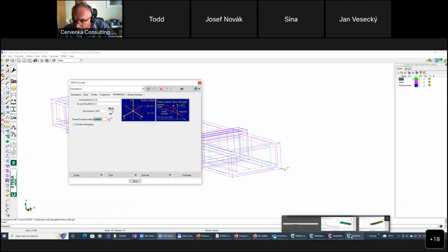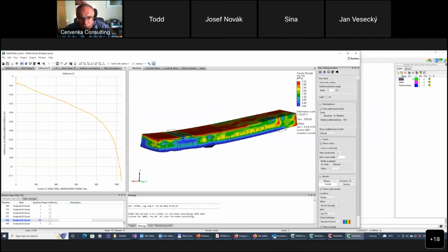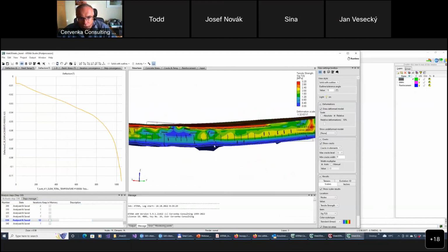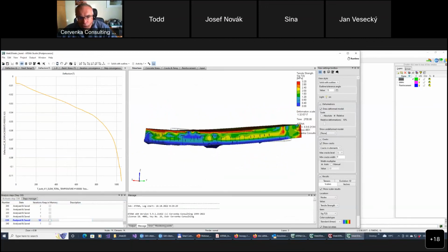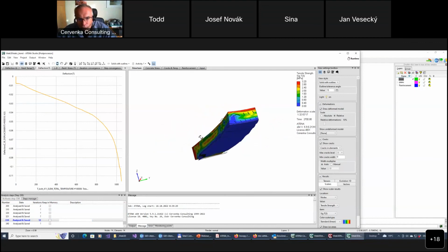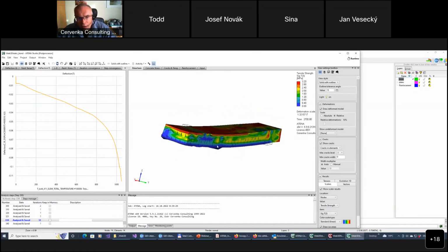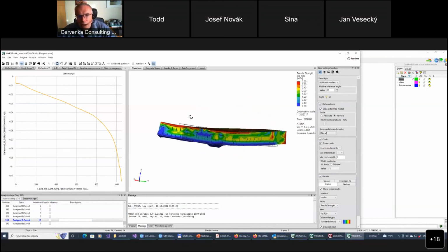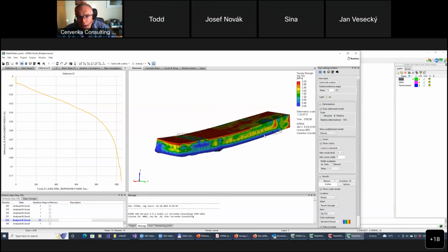And actually, if you look at the results that I showed you, you see that even our model without this water pressure is exhibiting this spalling. You see how this first layer of concrete is being cracked away. That's the consequence of this huge pressure, which builds up here due to this expansion. You even see how these concretes are separating a little bit and trying to leave. They have almost zero strength anyway. So this is somehow addressed in the current model as well.